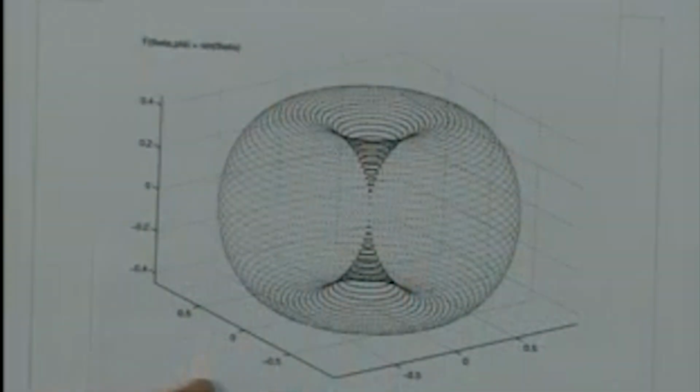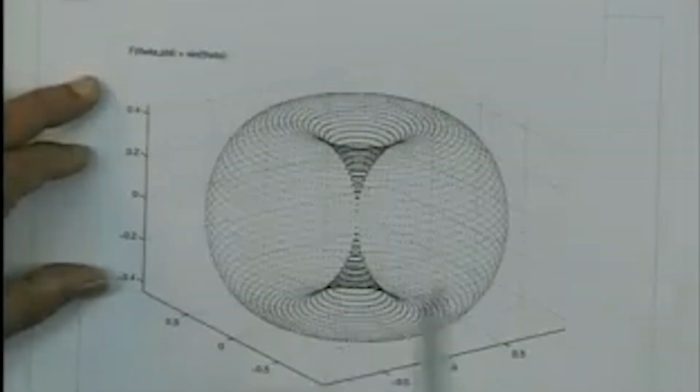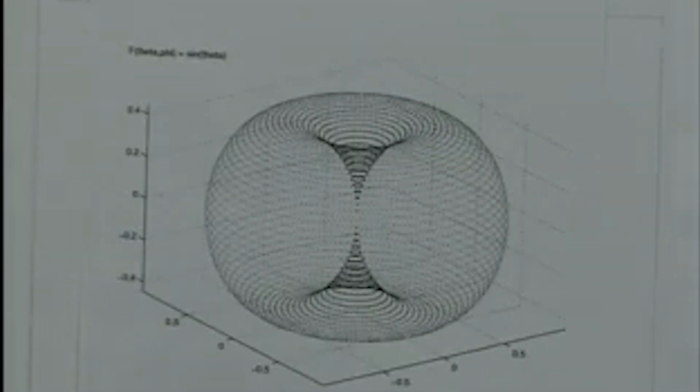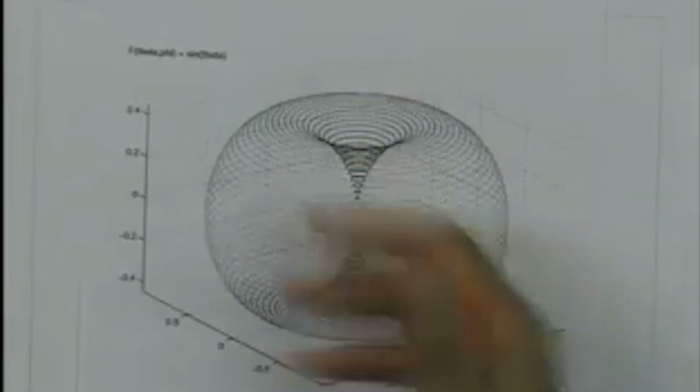Remember also, the radiation pattern is a 3-dimensional figure. Essentially we are drawing the variation of the electric field as a function of theta and phi. Therefore we get this 3-dimensional surface, and that is what we call the radiation pattern. However, while drawing or discussing, it is rather difficult to draw 3-dimensional figures, and since this is a simple figure, if you take sections of these figures, we can still get the information about this 3-dimensional figure.